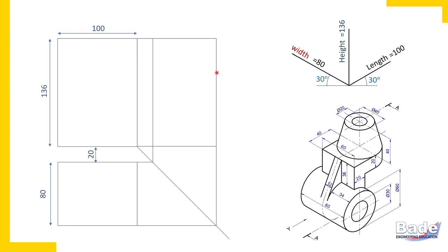Now this is a new instruction. No, not at all. I'm giving you an instruction I've given you many times earlier. Now watch here. The object is symmetrical. Front side and back side are symmetrical. So it's always better to draw the axis of symmetry immediately if the object is symmetrical, immediately after you construct these three rectangles. Front and back symmetry it is.